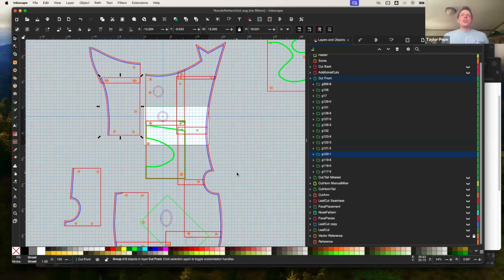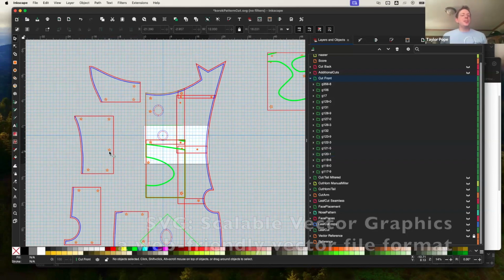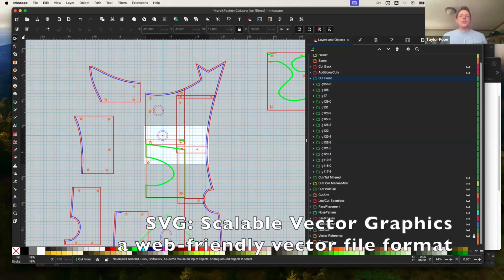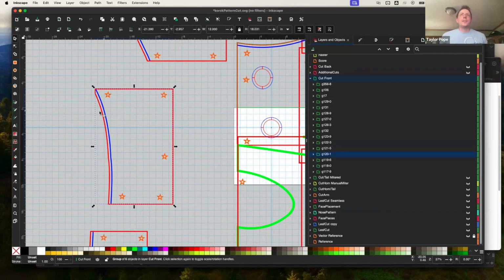But when you want to use the cutting features of a laser, you need to have something that is made of individual lines rather than pixels. This is largely going to be working with SVG files. And likewise, if you're looking for things to cut out on a laser online, SVG is the key term I would search for, because scalable vector graphics include the right information.